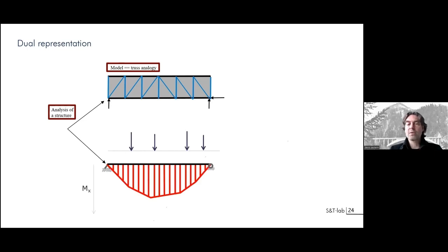The fact is that for several materials, as for reinforced concrete, for instance, this approach below cannot help you to assess the resistance in shear forces, or rather calculate what reinforcement you have to implement in your system, with the spacing of stirrups and the actual resistance of struts. So the same problem can be represented in several ways.